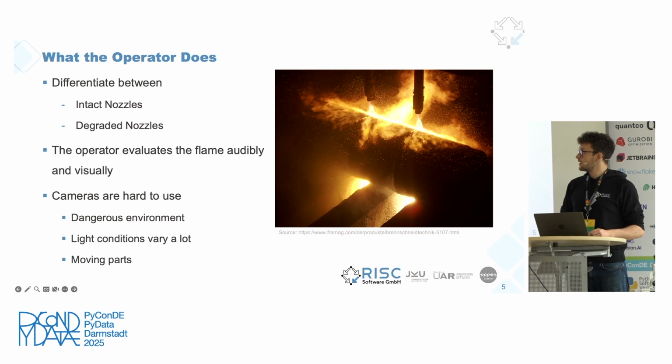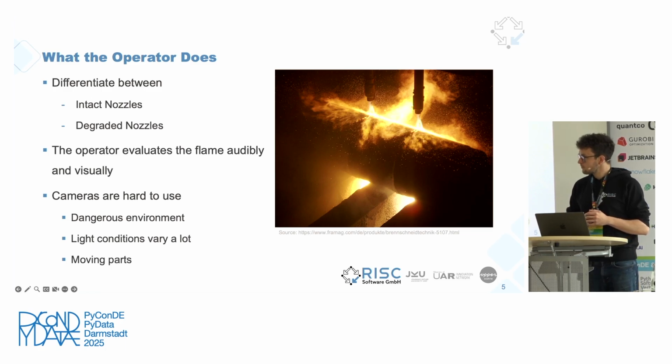which works quite nicely. What the operator does when he gets back such a nozzle is he wants to differentiate between intact nozzles and degraded nozzles. Degraded nozzles are usually visually not different, but the flame can look different and they sound differently. So the way the gas comes out from the machine and the flame sounds while burning can be different.